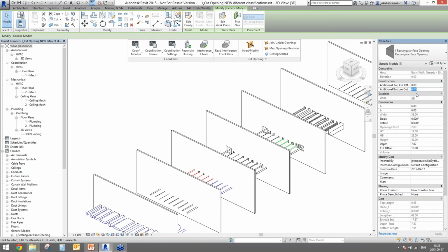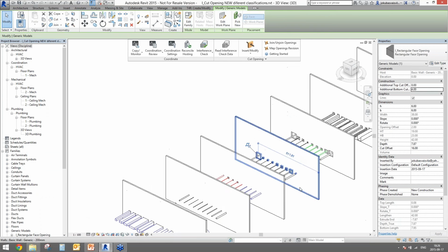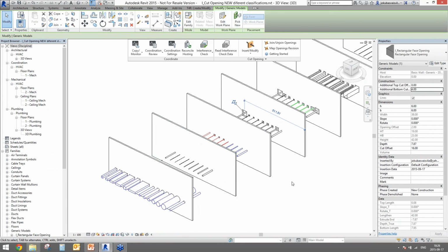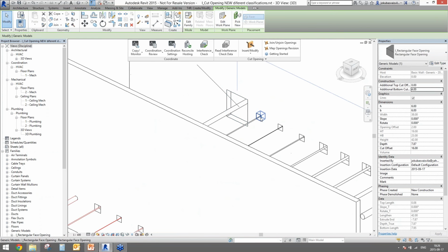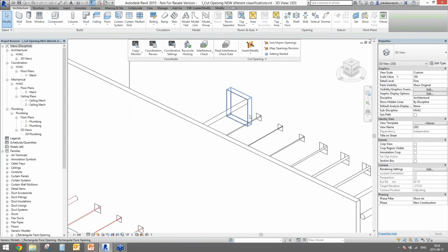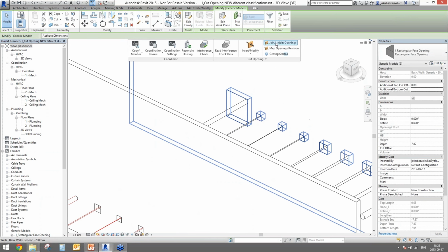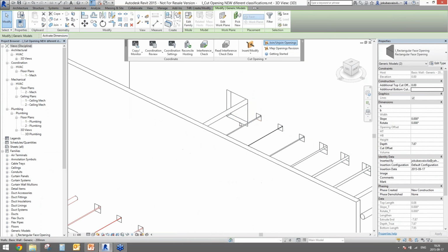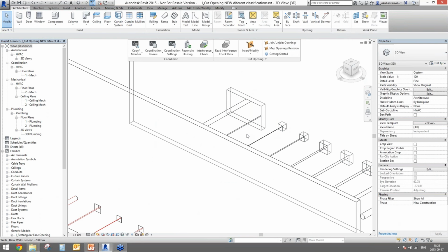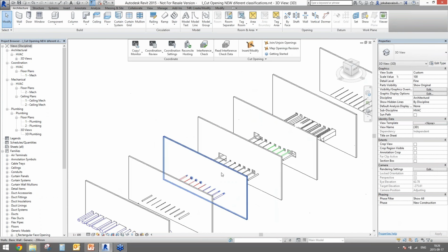additional inches. Sorry, I'm from Europe, so I do not know how to use these inches and so on. So I'm very sorry about that. But it is working in a model as well. I want to say that you can auto join the openings just using simple join opening configuration, and it will find the extremes of your openings, and it will auto join these 2 openings as well.